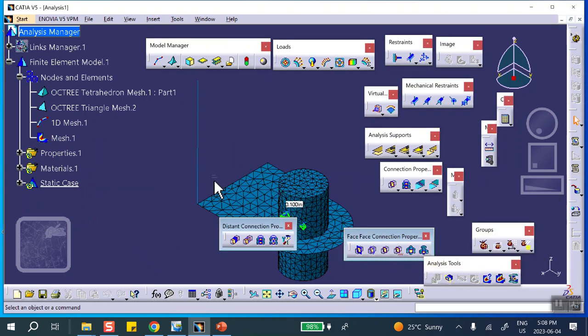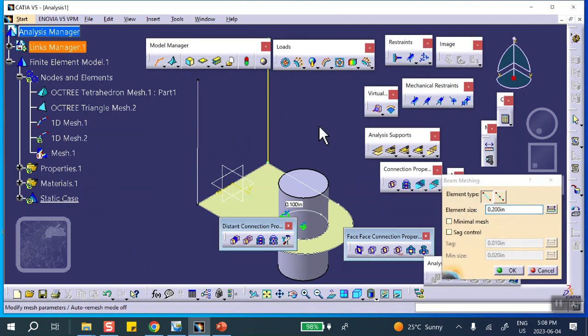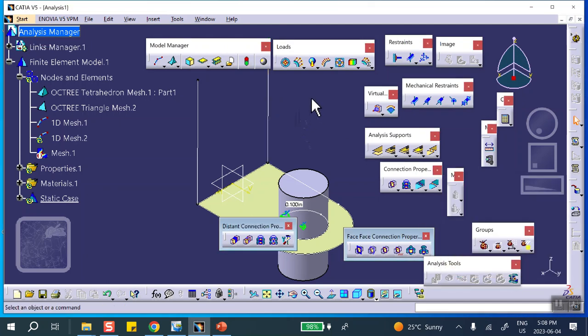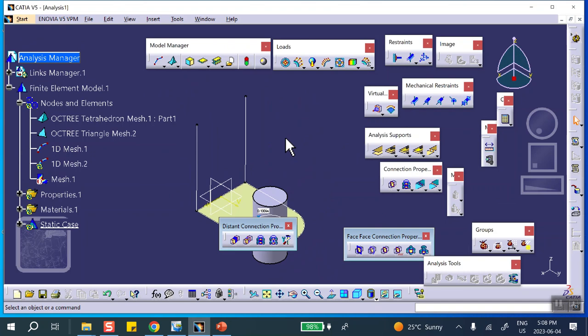These beam elements are also here. Deactivate once again. Do the other side. So mesh this side. I didn't have to join because this was a wireframe. It was done as a line in space. Don't forget that if you're using beam and you're doing it in sketch, you have to join first.